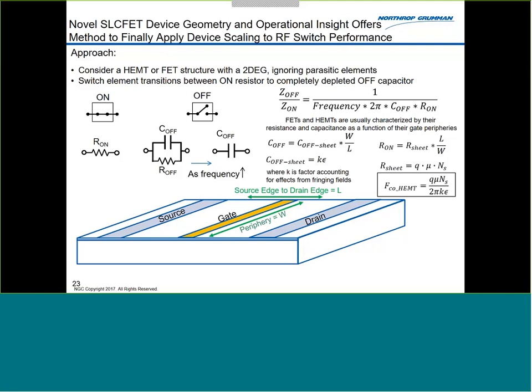I'm going to confine myself to switches at this point. One of the primary qualities that we want for a switch is that it's low loss, which means that we don't have any dissipated heat within the device if we're making it properly. Even at really high powers, several watts, and I'll show you the data a little bit, we're talking just a few tenths of a dB of loss, which translates to maybe 100 milliwatts of dissipated power, even for a 36 dBm signal.